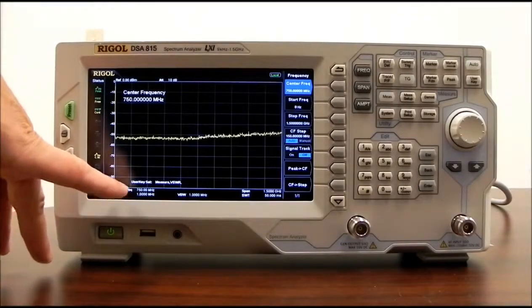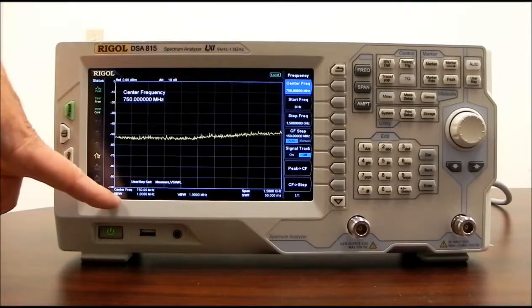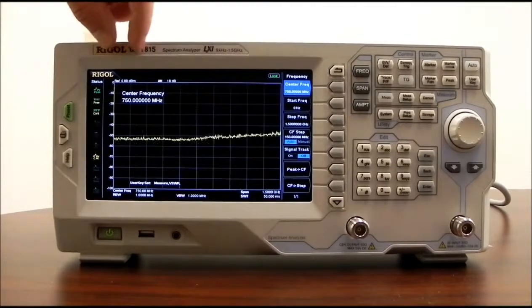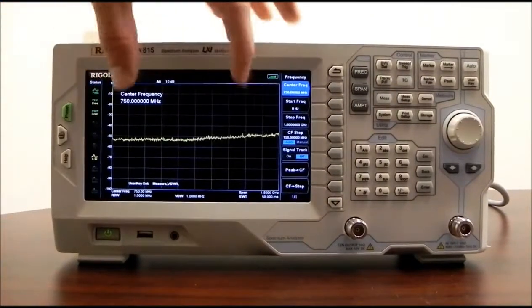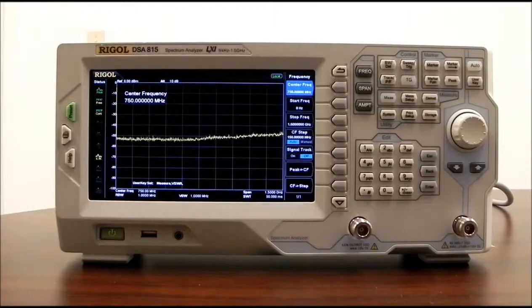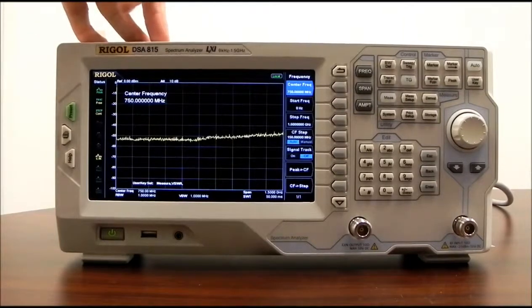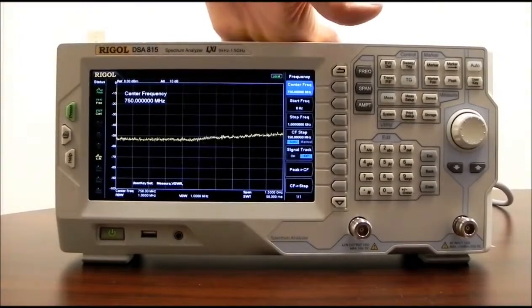So down on the bottom here, we're indicating our center frequency, 750 megahertz, and resolution bandwidth. Resolution bandwidth is the size of the detector opening that is then being scanned. The wider that resolution bandwidth, the more spectral content we're taking per frequency step as we're scanning through. So we have less resolution, but it scans more quickly. By shrinking that resolution bandwidth, we get a much higher degree of resolution, but each scan then takes longer. It's sort of a catch-22, I guess, of the spectrum analyzer.